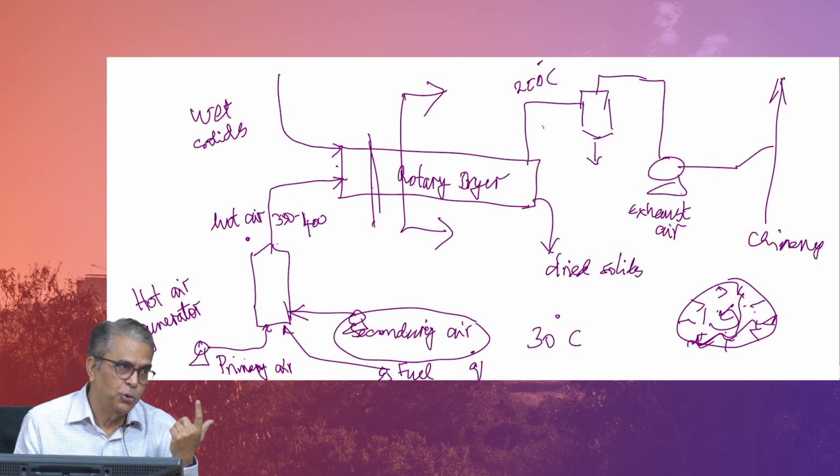You have to look at new equipment, so cost adds up. Same story for the secondary air fan also. It was just drawing from atmosphere, putting it into the furnace. Now you are putting one heat exchanger into it, so the pressure drop you have to work out. So, that is then how the gas from here to here has to go.